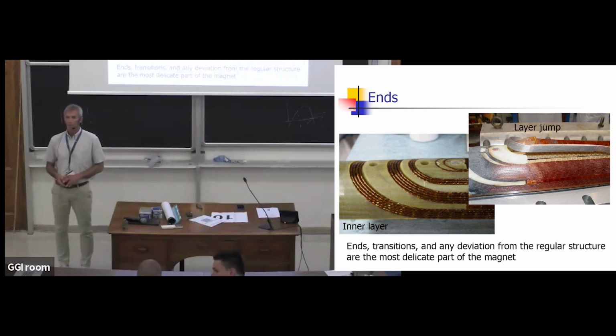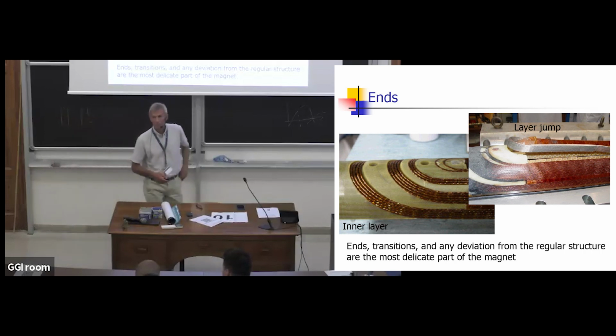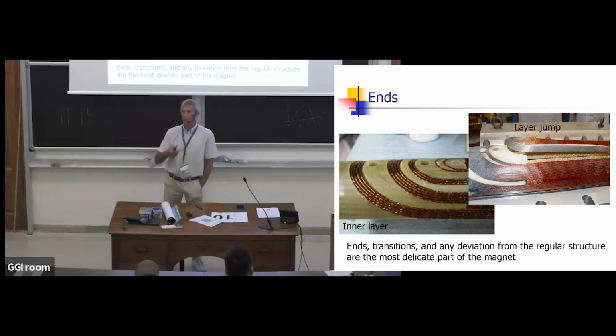So now I have a second question after you showed that. With REBCO, hypothetically, will it be the same coil or braiding as you have for niobium tin, or what do you think the manufacturing process will look like? How thick, how many layers of REBCO do you think we'll need? Right. With REBCO, you can wind the same. It's a single tape. You can do cosinus theta. You can do blocks, and blocks are, if you wind like a racetrack, and then you lift it at the end so that you make space for the beam.